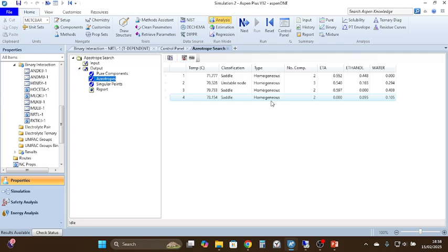The reason is that benzene helps to remove the water from the ethanol because they form a ternary azeotrope at that particular point. That is why two liquid layers are formed. These situations usually happen whenever we handle three components in which one is more miscible with the other, so naturally they combine together.